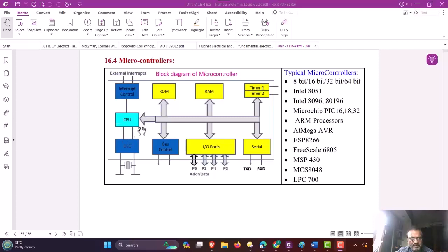The central processing unit consists of an arithmetic and logic unit to support the arithmetic and logic set of instructions. Second, it provides the internal scratchpad registers to store the intermediate data. Normally the scratchpad registers in microcontrollers are much more than in a general purpose processor.